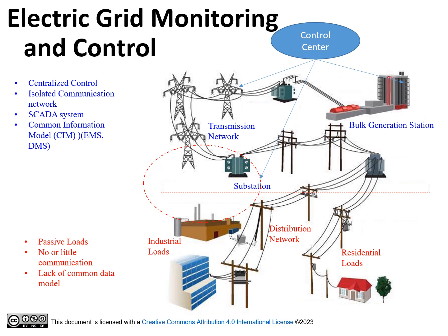The conventional electric grid is not only characterized by central generation, but also utilizes central control to control generation power plants and transmission networks. Substations and generation power plants are connected to centralized control centers. Transmission networks are monitored and controlled remotely using SCADA systems. Fiber optics and isolated networks are usually used to connect substations and transmission SCADA systems with centralized control centers.